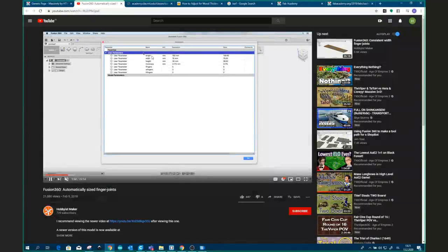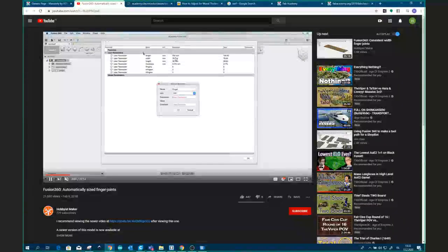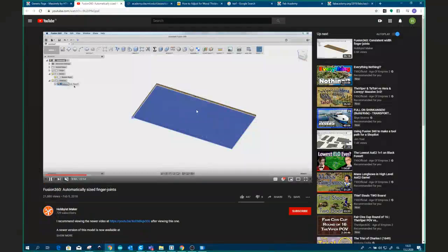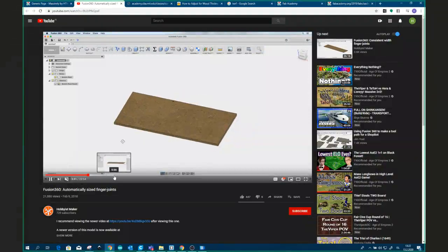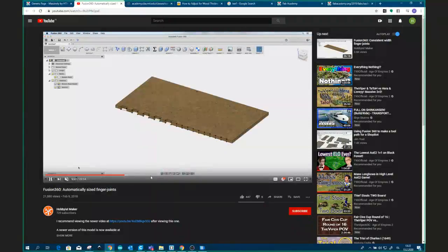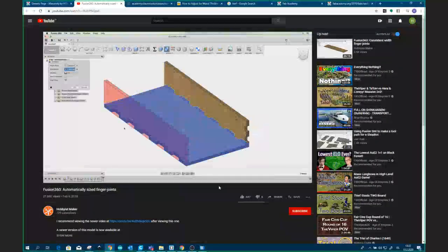You put a name to the variable, and then you express that variable with a length in millimeters or with a formula that you've designed and specified beforehand, and then you make your design based on the names instead of just the lengths. So you should be able to go back, change the variables, and that should ripple through your entire design and change the shape of it.